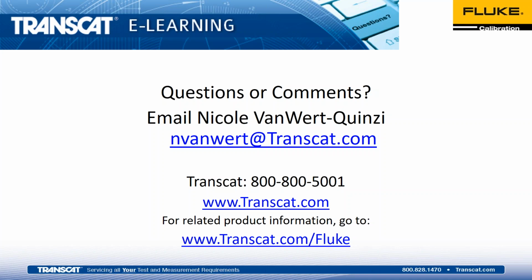Okay. Next question, is the 9190A only used to calibrate RTDs? No, again, it's just a heat source, so it can be used for RTDs, thermocouples, TCs, other sensors. It's designed to be a stable heat source with a usable range of minus 95 to 140 C.